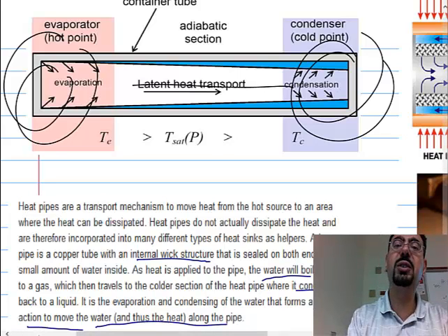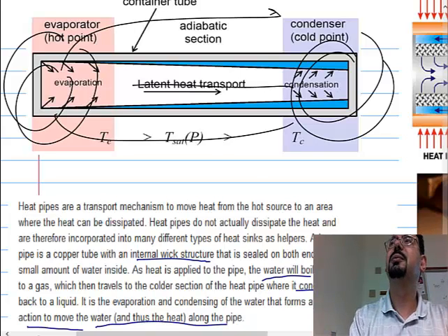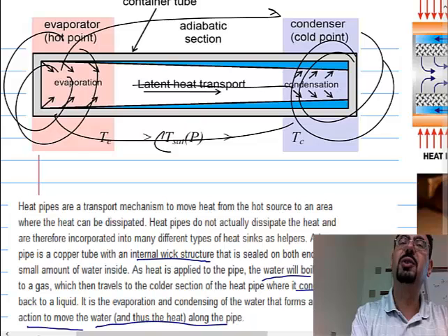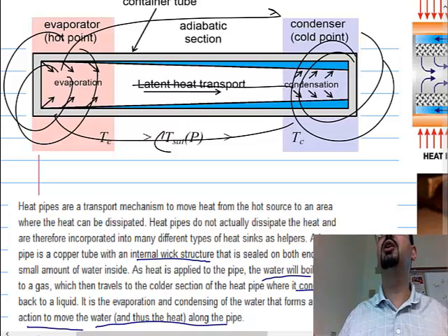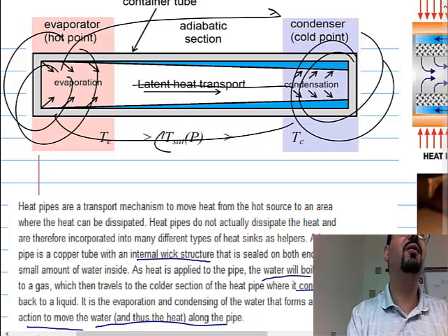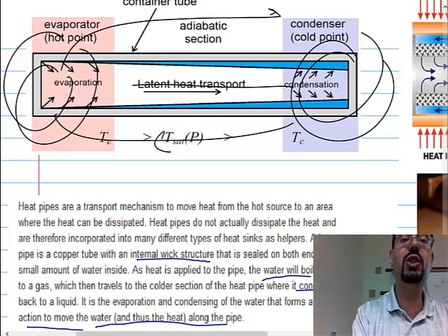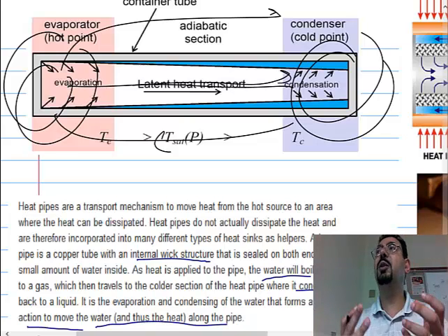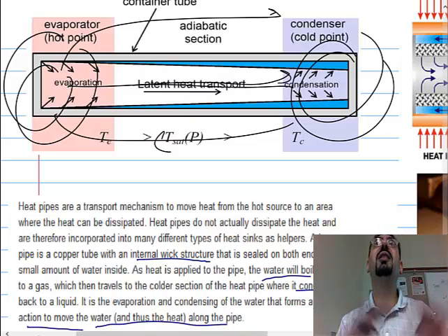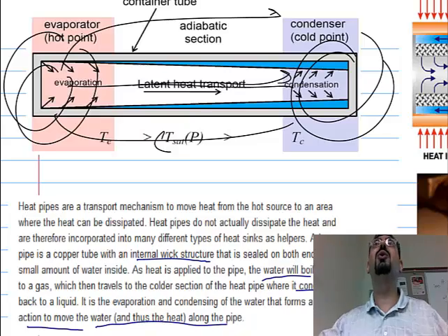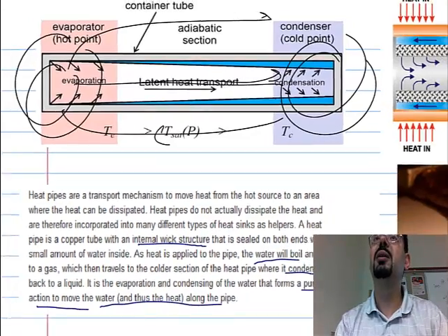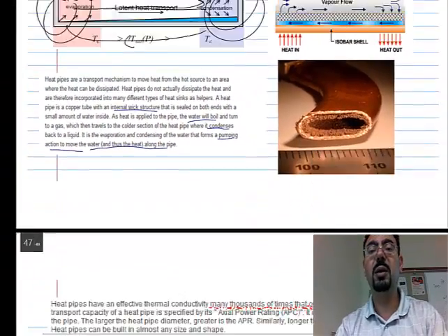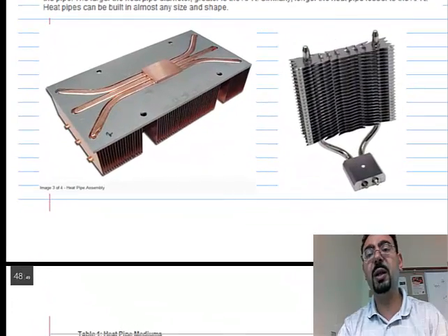And so you have high concentration of water, low concentration of water, and this pump is continuously bringing the water from here to here, so that it boils. The vapor, because it has large volume, doesn't have to depend on the wall to move. By its pressure, the moment it forms, it will just fill the space and go to the other place where it will end up condensing, all right? So it would be something like this.